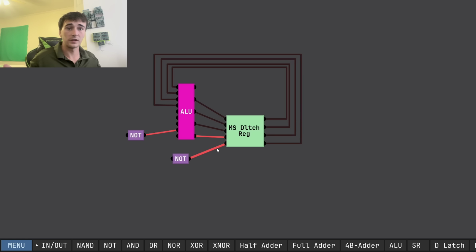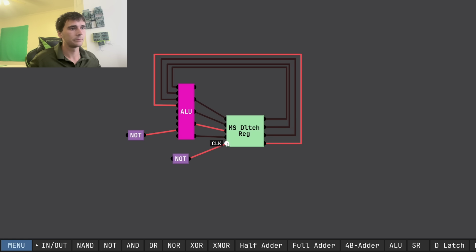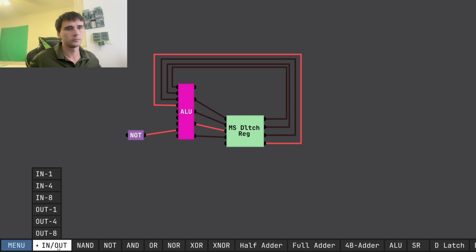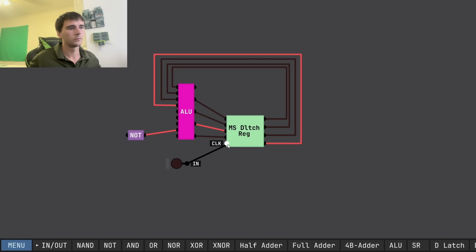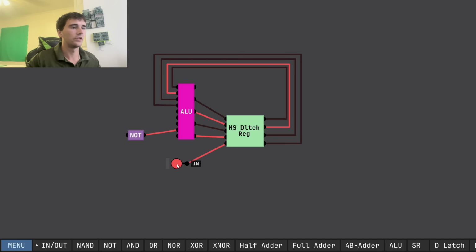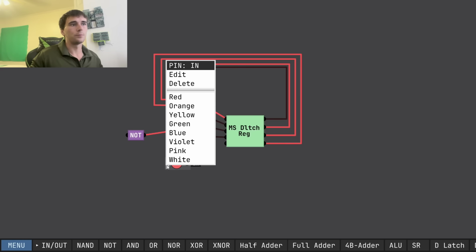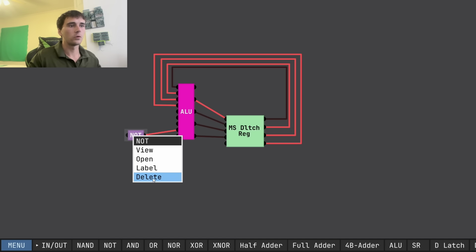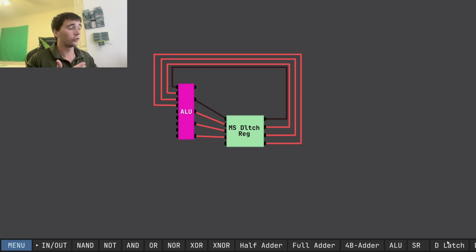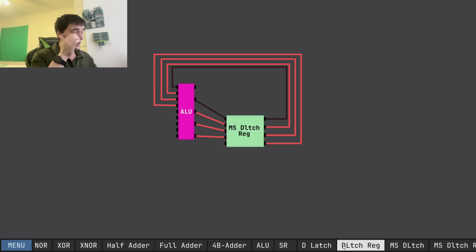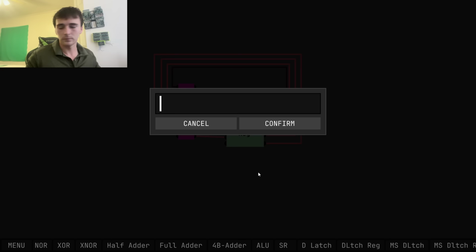And now we can add it relatively easily just by pulsing the clock. And we're just going to add by 1. So this works really well, actually. So we can kind of start building our CPU. And the design I'm going to use, or the architecture, is called an accumulator CPU. And it's called that because this main register right here is called our accumulator.